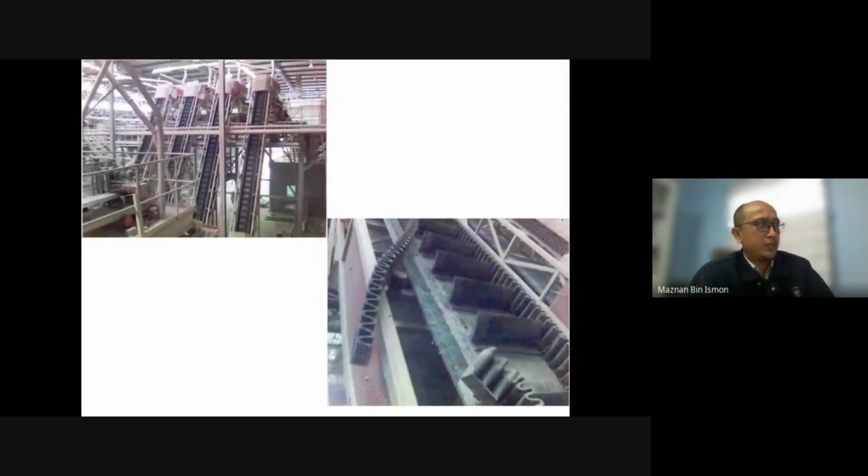This is a picture of a material handling belt. It is actually a flat belt, but it has this pocket, this pocket bucket over here, and it has a side wall over here. This side wall has come off, so the gum here has come off. By right it is a flat belt used to lift sand or other material upward.